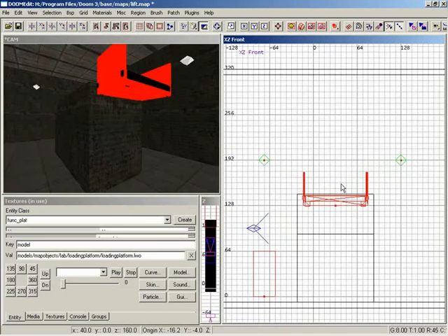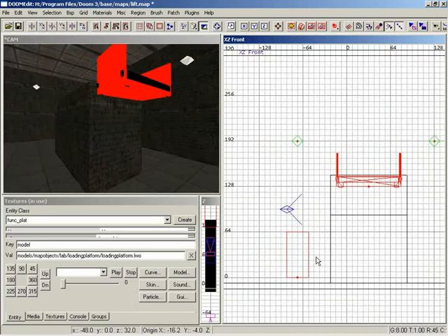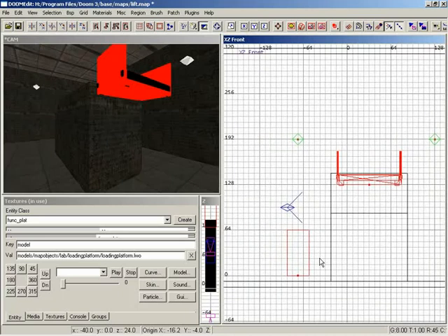So with this setup now, it's actually almost ready to work. And in essence it would, except that the height traveled is by default defined by the height of the model itself, which means it's basically going to start off just resting right under where it is now. We need it resting on the ground, so we're actually going to have to specify a height that this FuncPlat travels. So basically what you're saying when setting up one of these types of lifts is you use the object, you basically set it up to its maximum height.